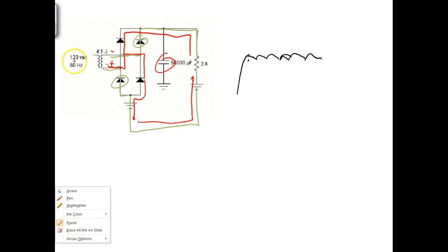So I plugged this in, we did all our calculations around 120 volts. But at your house, you might measure like 110 or something like that. Well, if the input voltage is different at your house, then my output voltage is going to be different, right? So what we're going to do with a regulator is we're going to compensate for different input voltages and also different output loads, which is going to be pretty neat.